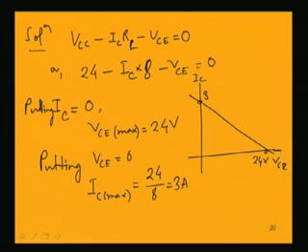So, you notice here we are getting 3 ampere, not milliampere. It is a power transistor. This is 24 volt. So, joining these 2 points, we get the load line, the DC load line. Now these two are the limiting voltage and current ratings for the power transistor.